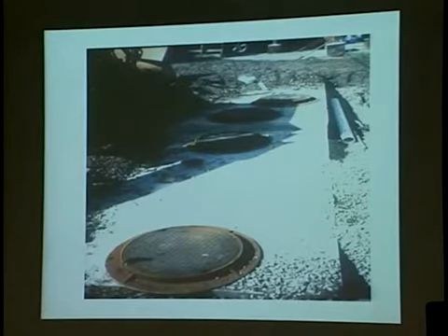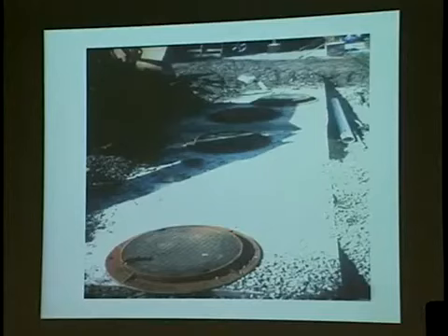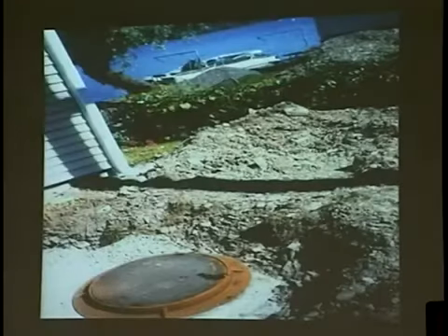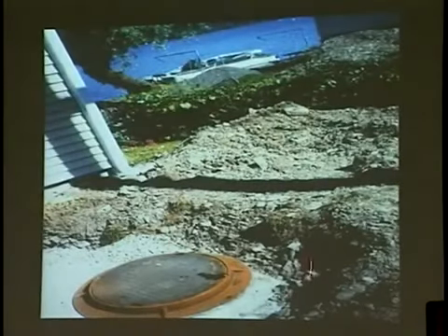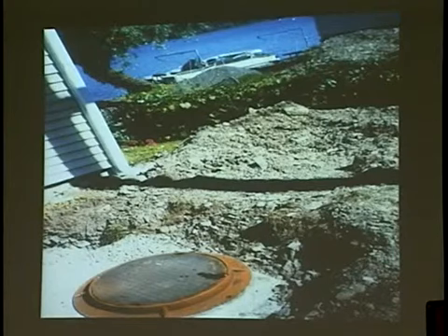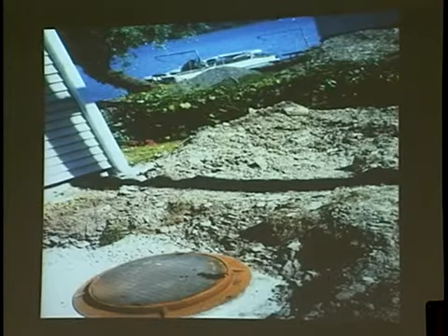So in this case, we put 2 tanks, I think they were 2 1250s, end to end, hooked them in series, put the high-level alarm in the far end tank. Minimizes their pump-out costs. Again, you can see the fractured shale that we're dealing with here. You can't put any type of a system on it and get any type of nutrient removal.